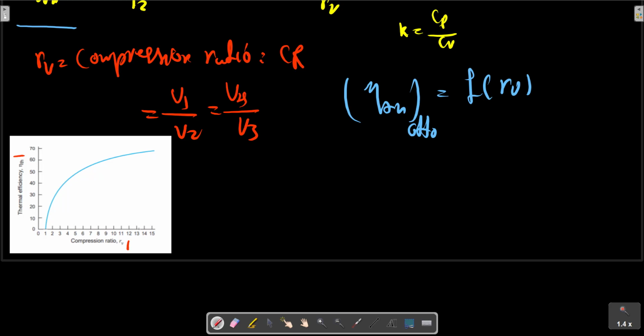Advances over the years in compression ratios in actual engines were originally made possible by developing fuel with better anti-knock characteristics, primarily through the addition of tetraethyl lead. More recently, however, non-leaded gasoline with good anti-knock characteristics have been developed in an effort to reduce atmospheric contamination.